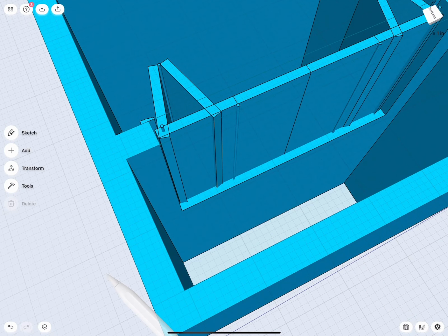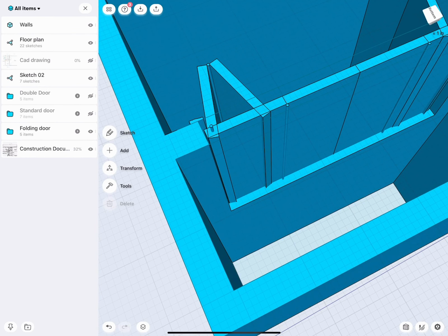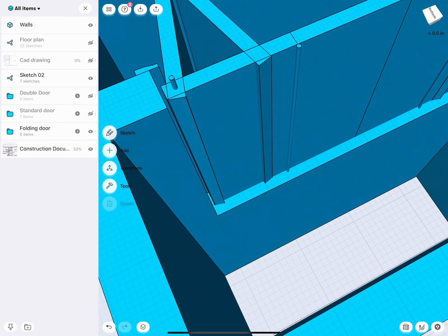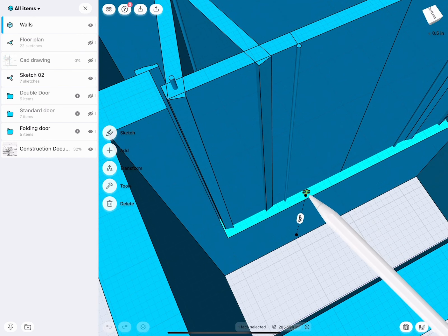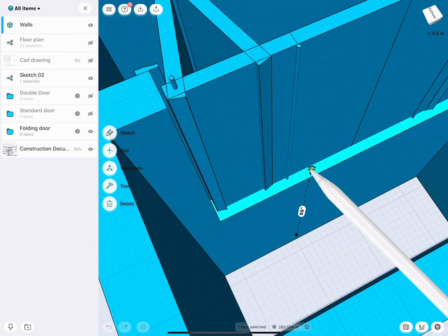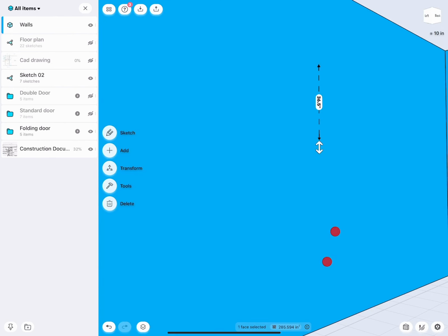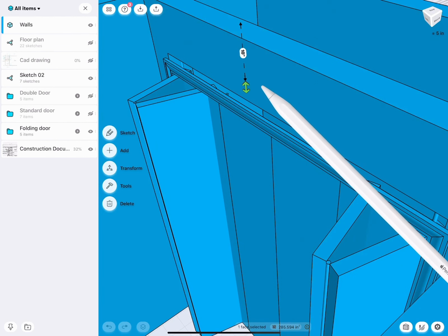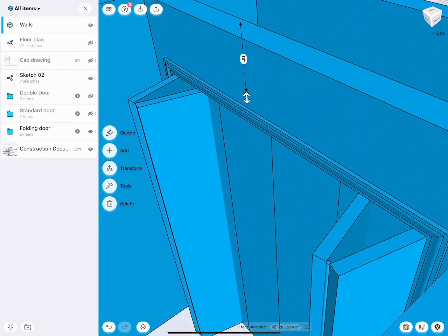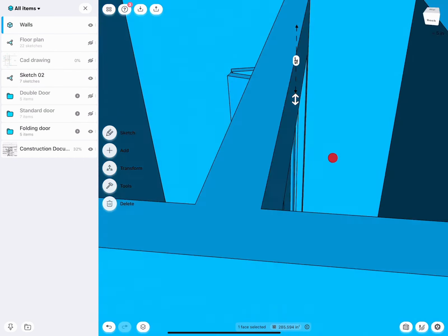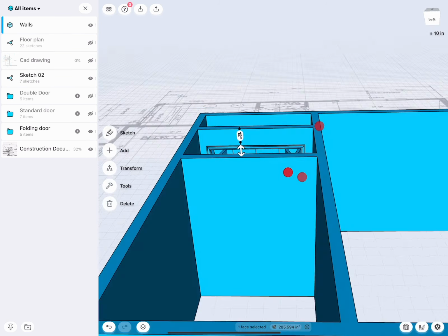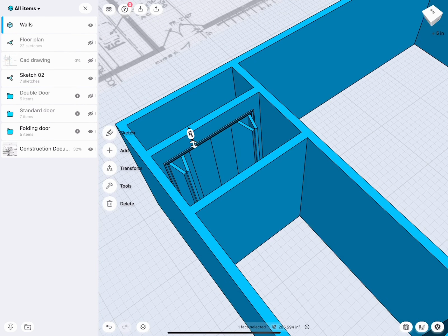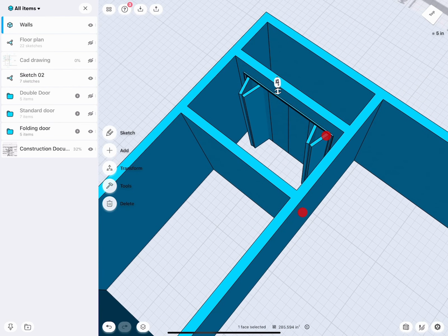And with all this done, now I can select the face here that is basically defining the door opening. And you see I can slide this up and down. And I just have to make sure that at one point I pull this one up as much as needed, so I have a little bit of an opening. Okay, very good. So one of the problems I have here in the space when I went to the client is also it has carpet, so I couldn't really measure from the ground, so the subfloor. So I needed to approximate a lot. And as you can see, this is actually a very, very easy way how to do this.